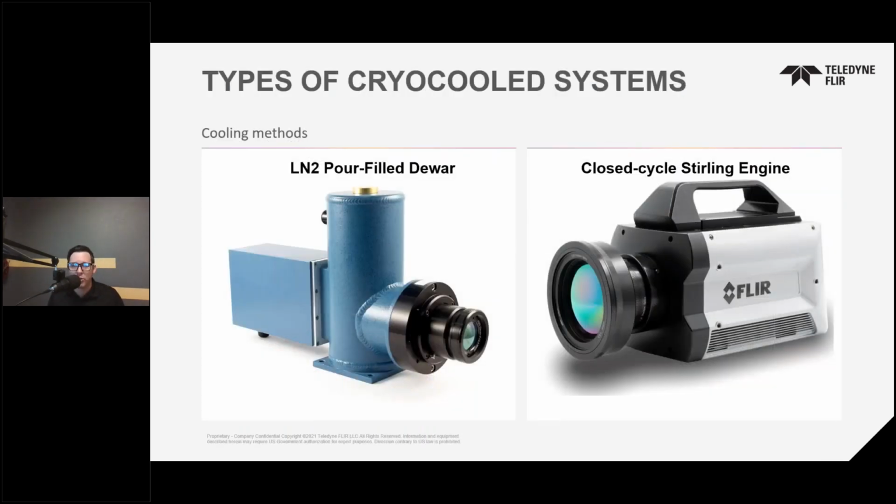So cryo-cooled systems, photon counters, cryo-cooled detectors, they utilize a hybrid detector that's created by combining a focal plane array of some unique material, like we just talked about, like an example would be InSb, or indium antimonide, with an electronics package that's referred to as the ROIC, which is the readout integrated circuit. So it's just a sandwich detector of this unique focal plane array material with that electronics package. That's why it's called a hybrid detector.